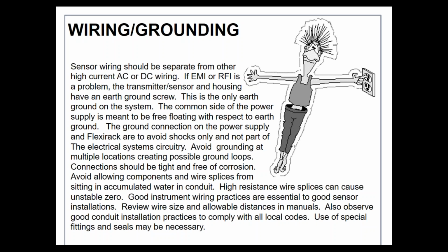In the case of GasTel, that light absorption signal is being amplified about 1,800 times. So the gain turned up on gas detectors is huge. Therefore, any little glitch, any little bump, any little electrical or EMI/RFI can be amplified as well and give you a system that's not reliable.